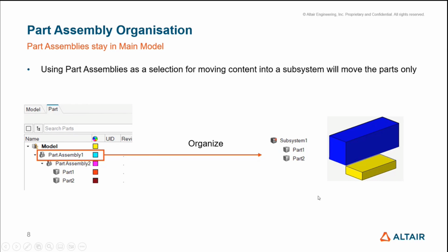I should note at this point, if you do the same thing and you organize a part assembly into an include file, there's this pop-up move to include organization dialog. That will still allow you to select the part assemblies because it's based on references, and so you can trick that one into picking part assemblies and move the part assemblies into an include file.